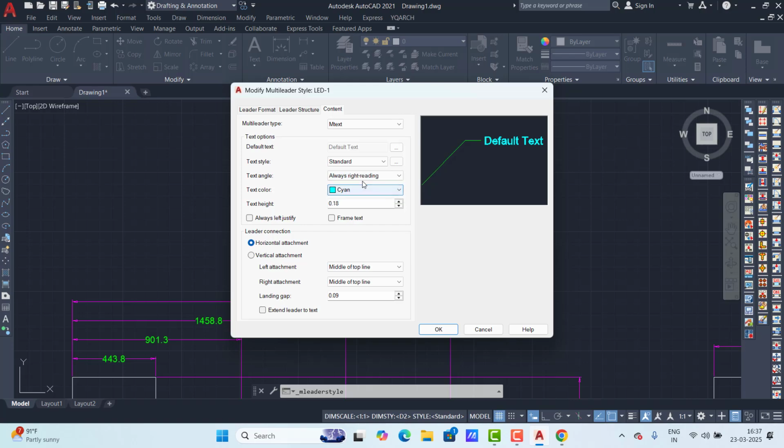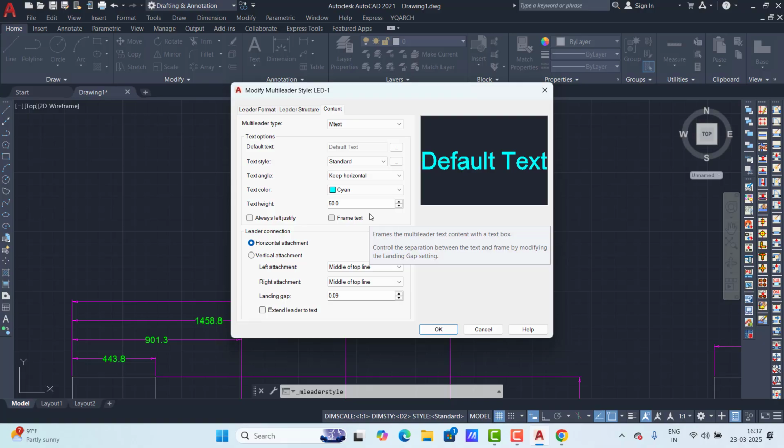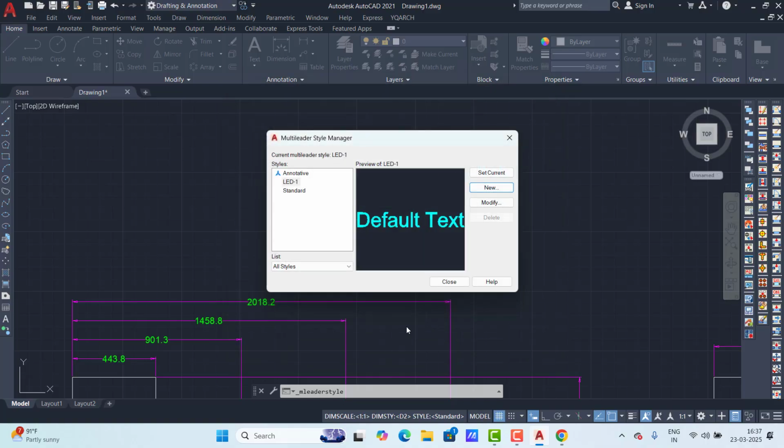But when you manufacture properly, every time it does not come 1076; sometimes it comes 1075, 86, 80, 85, 90, sometimes 1076.123, this type. So if we take one value, that is not possible. So how much variation we can manage, that value can be presented with the tolerance options.